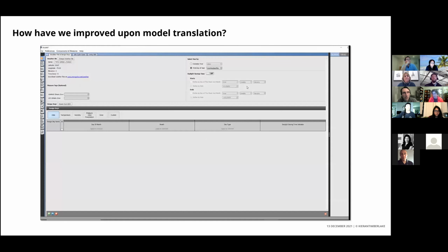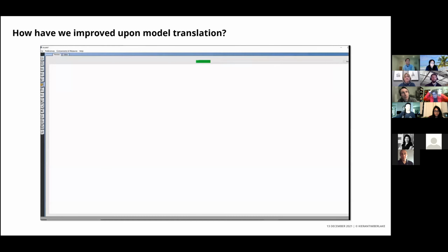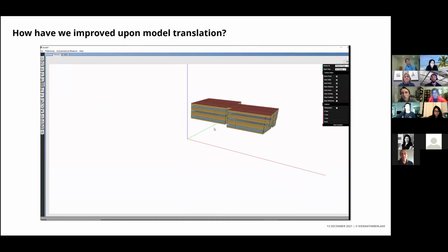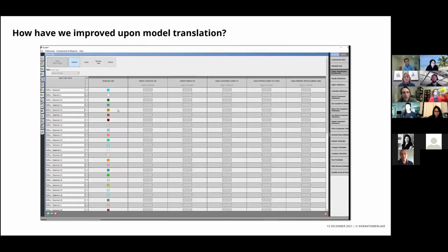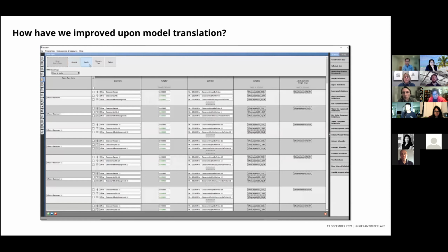So starting with our NYU Mercer Street project, which had around 500 thermal zones, so a very large project, but then continuing over a number of projects over the years, we've developed a workflow wherein we can maintain a really nice clean set of energy model plans within our architectural models, and at any moment spit out to our engineers a really nice clean OpenStudio model for them to iterate with.